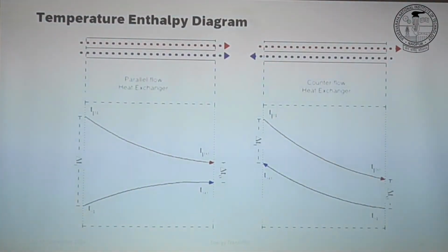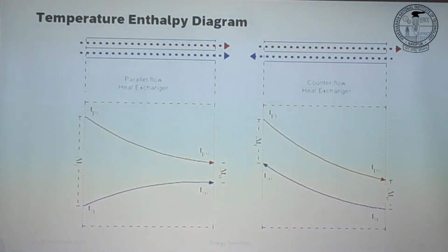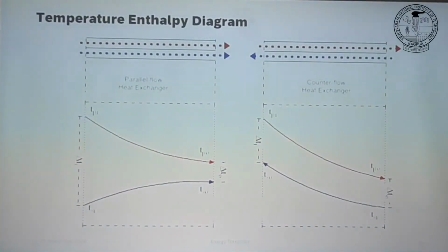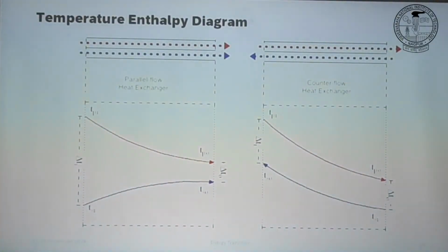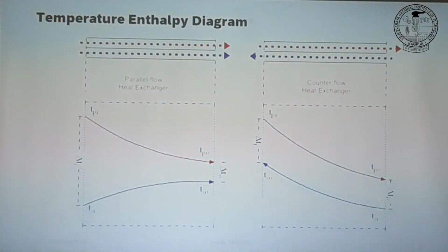Now you have not one pass, you have two passes. How will your pressure drop increase on the tube side? Think about it, you have reduced your flow area by 2. And how is flow area related to pressure drop? Delta P is 4fL V squared over 2gc D. V squared, V is nothing but flow divided by area. If you reduce area by 2, effectively the pressure drop will increase.